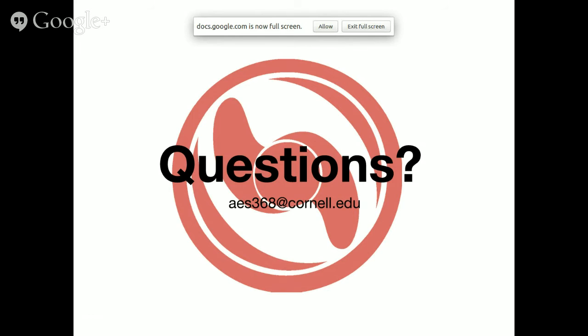There are a lot of teams out there that do a controller in firmware. That might work better. I guess it's more real time, you have more updates, but we found that it's nicer to have this kind of ease of access and ease of tuning to the controller. And of course, speed isn't really an issue. We use Python for our controller. NumPy is great. It gives you the speed of C with the ease of use of Python. So our controller runs just as another Linux process on our submarine, and it's worked out quite well for us.